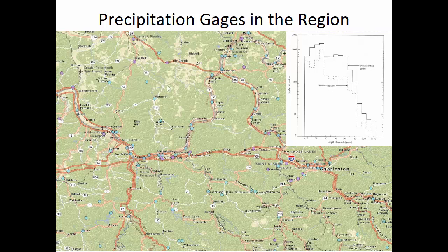Well, to really know what the 100-year storm looks like, you'd need 100 years of storm data, and you may not have it. And so there are ways that we can extrapolate, maybe if we have information on what the 50-year storm looks like. If you had 50 years of storm data here, but then there's another spot where you can say, well, the 100-year storm is 20% larger than the 50-year storm, and that seems to be a reproducible trend in places that have the same kind of topography as Waterloo, then we can extrapolate.